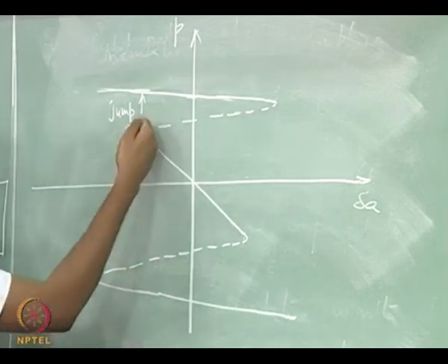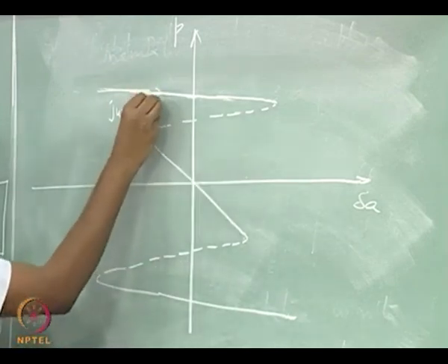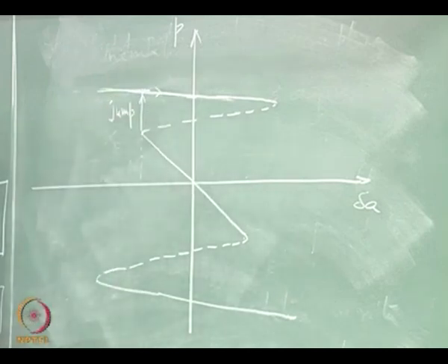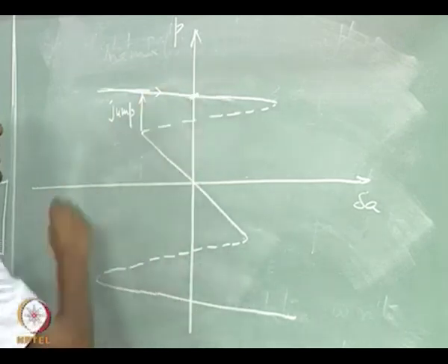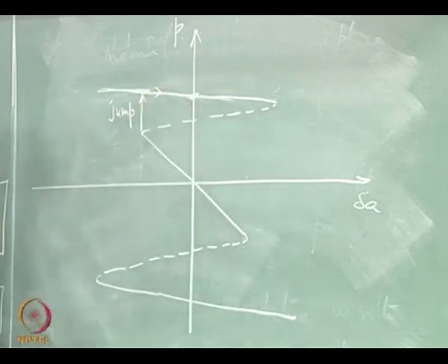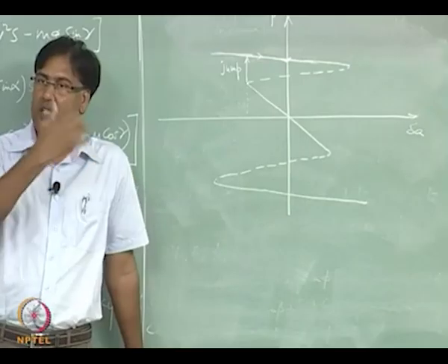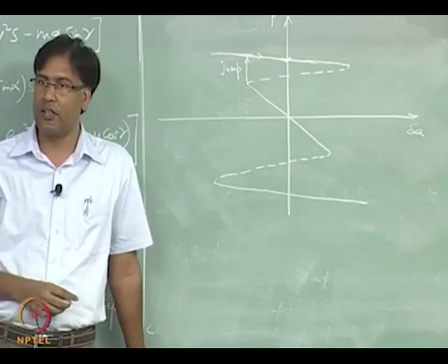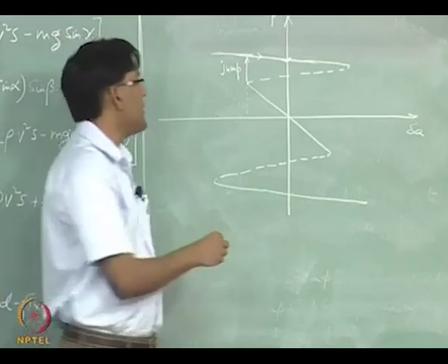When you are doing that, you are decreasing aileron, you are actually moving onto this solution branch, right, and there is a situation when you have brought back your aileron to neutral level, but you still see a positive roll rate, isn't it?